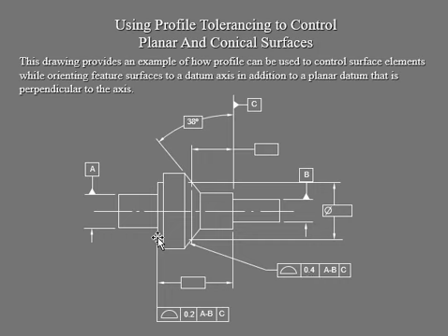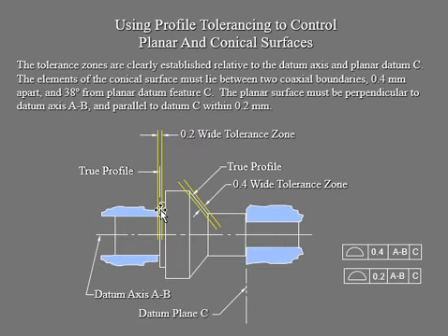Here, make sure that you take a look at where it is attached, so you know which profile the tolerance zones are defining. Right here we have two datums, A and B, in order for us to deal with this profile. Of course, for this one we're going to use A, B, and then C, which is here, because that tolerance is going to cover from here all the way to here. Then we're going to establish our datum and bring in our simulated surfaces right there.